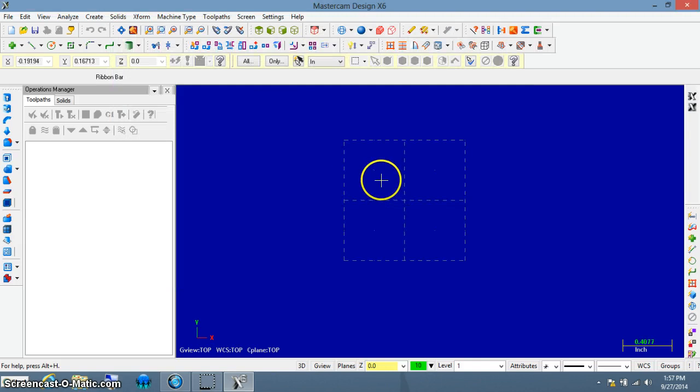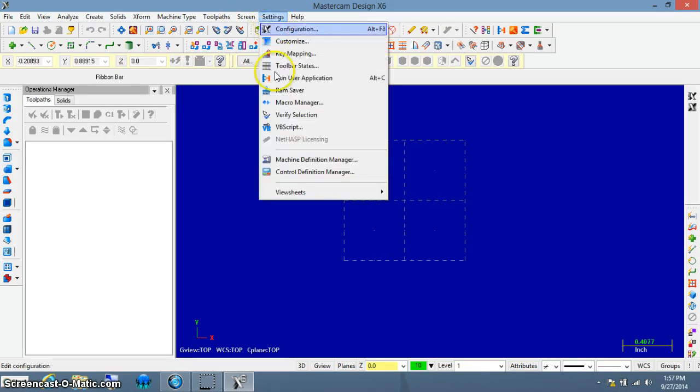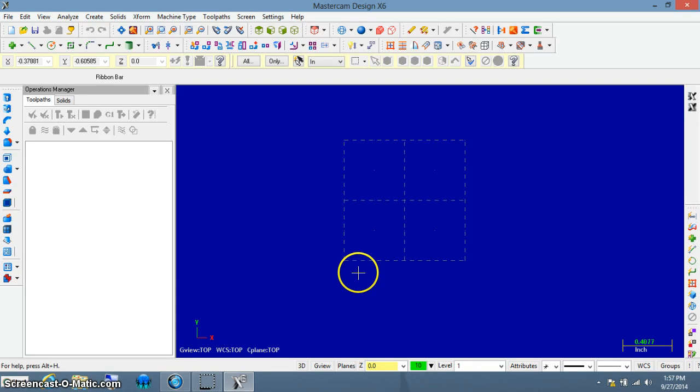What we've done here is we put like a reference point on your workspace, and this kind of indicates the program's coordinate 0. And if you open up Mastercam in the days to come, and you don't see this little reference, square of dotted lines, all it means is you're going to have to go through the settings setup again, configuration, default, and set that up. But if you launch the same machine each day, you won't have to do it. So that's incentive to open up the same machine each day.